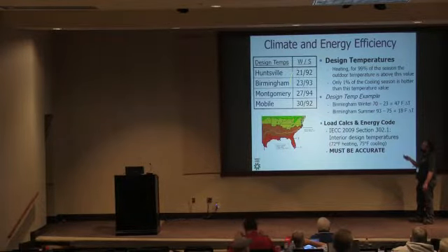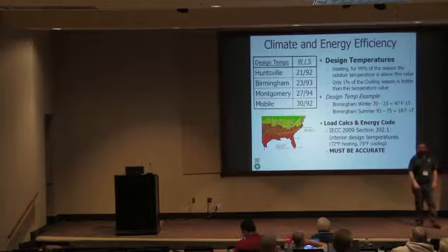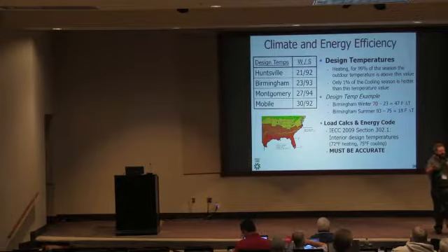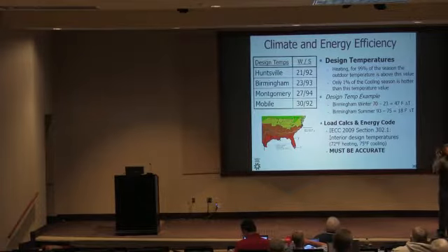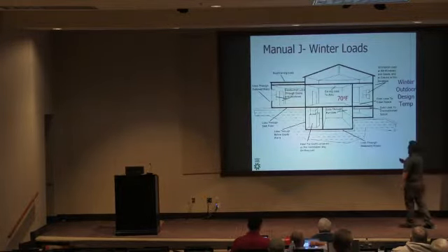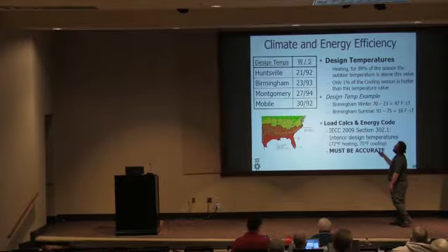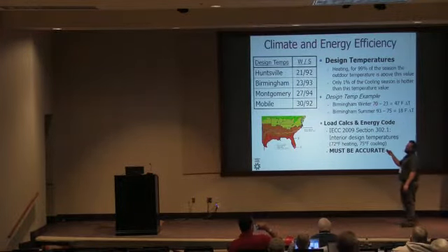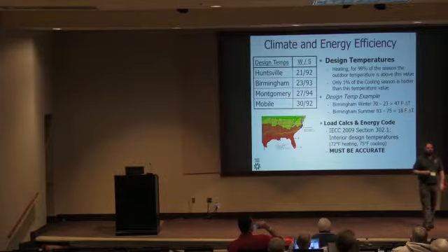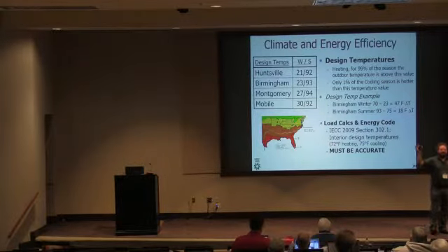And these are in ASHRAE, and this is from Alabama, sorry, but it tells you the winter and the summer design temperatures. If you have access to a load calc and you're only going to look at one thing, this is probably the first thing to look at, because it's the easiest thing to tinker with. I want a little more load, so I'm going to make my summer design temperature in Huntsville be 97 instead of 92. All of a sudden, I need a bigger HVAC system.